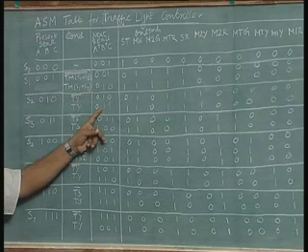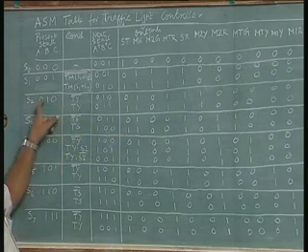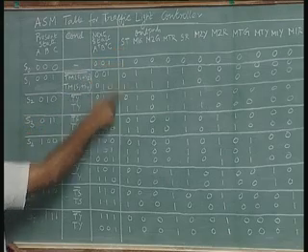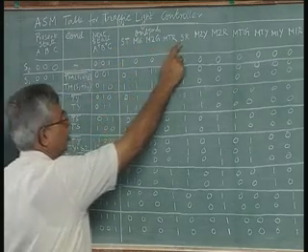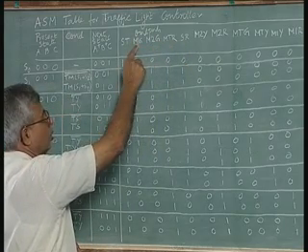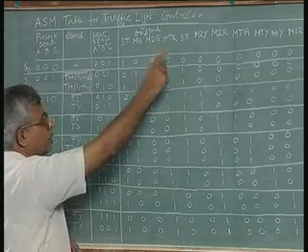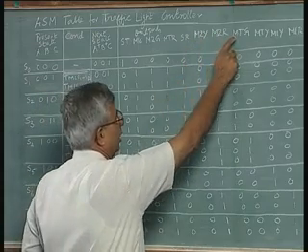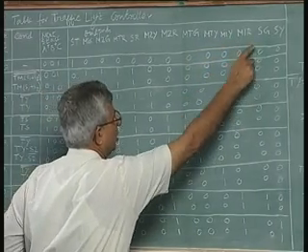After that, you go to the next state, and so the lights are correspondingly marked here. No start timer. The start timer will come only when you want to go to the next state. Whenever you want to go to the next state, you start the timer. So ST stands for start timer. These are output signals. These signals are the light signals corresponding to the lights. M1G, M2G, MTR. So main M1 green, M2 green, main turn red, side red, M2 yellow, M2 red, M turn green, M turn yellow, M1 yellow, M1R, side green, side yellow.